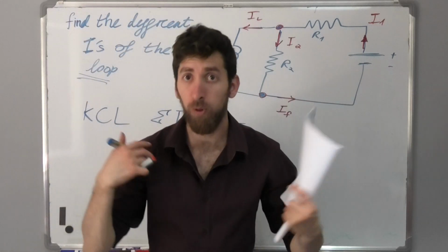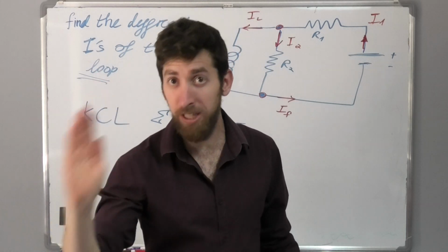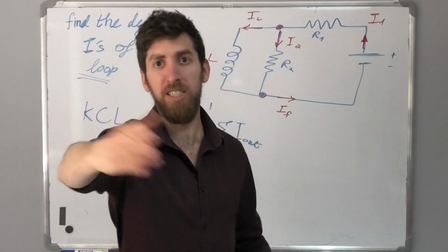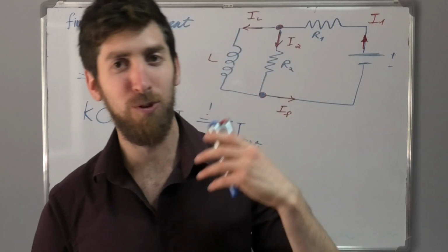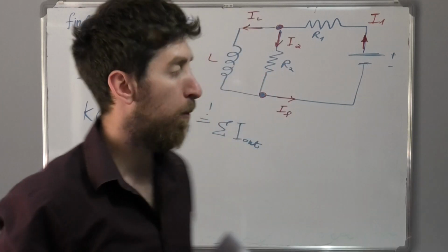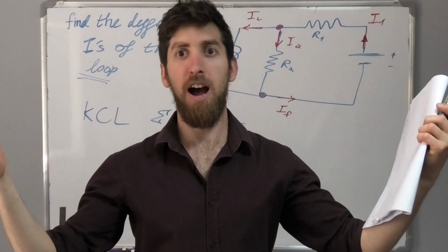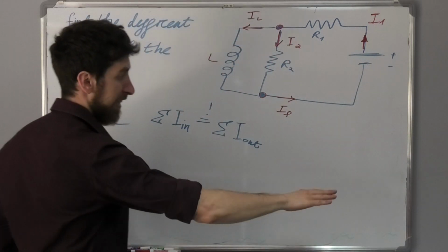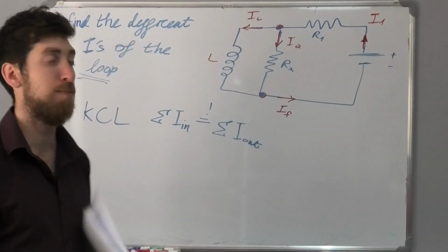If I have some river with a lot of water, and the river is actually split into two rivers, the contribution of the water going to the two rivers must be equal together to the original one. For example, if I have 100 liters per minute going in this direction, and then it's split out to 20 liters per minute, then the other side must be 80 liters per minute. That's what's coming into the junction, and then it's split. So the idea is what's going in must be equal to what's going out. We don't expect something to come out of nowhere, okay? There's no generation of current and no dissipation of current. So if there are electrons going in this direction, they're gonna split in some way, and the sum after the junction and before the junction must be the same.